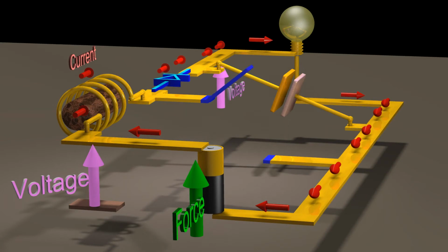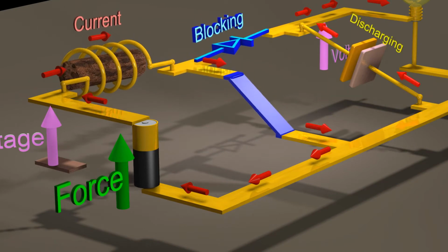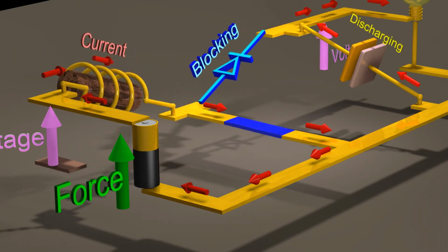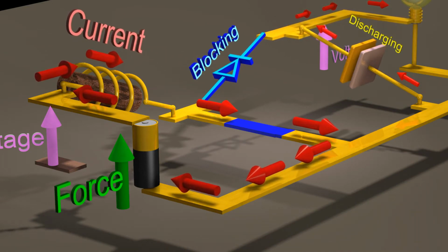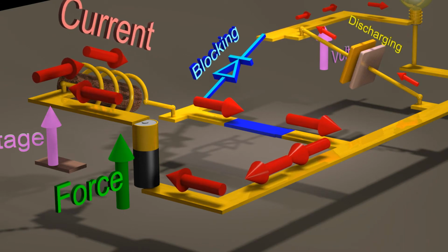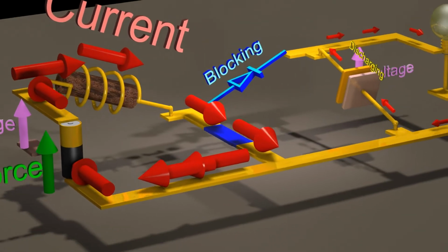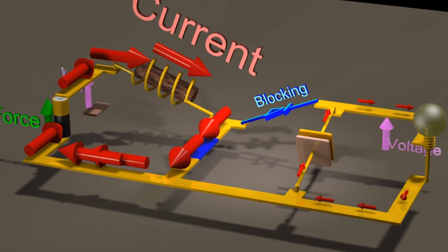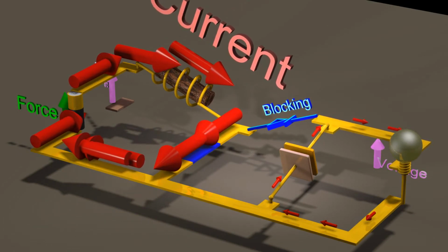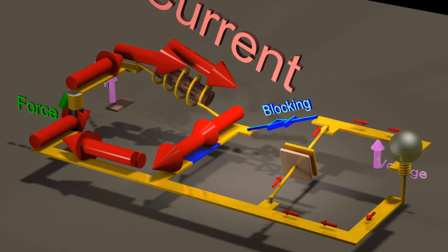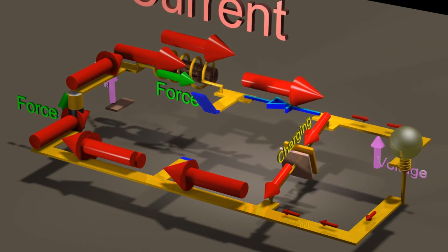What if we instead have the switch on most of the time? If the switch is almost always on, then assuming we have ideal components, the current will theoretically keep increasing to infinity. During the brief moment when we turn the switch off, an infinite current would charge the capacitor to an infinite voltage.